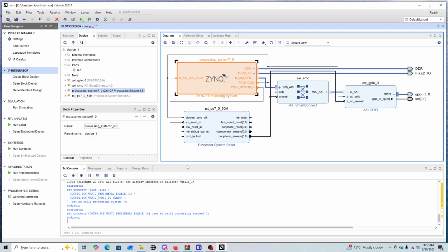How it works is I'm going to go through the processing system to the extended MIO pins, and that's going to feed into the programmable logic some of the free IO pins available, and that's going to route to an external FTDI chip. So once we get that functional, we're going to run some of the DDR3 tests that we could have run with UART functionality, and we'll see how to set that up in Vivado and Vitis here. So let's just get started.